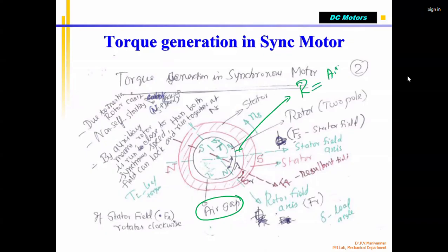Air is very poor compared to the stator and rotor, which are made of magnetic material. So that means for any given motor, whether AC motor or DC motor, the air gap should be small, but it should not be too small, because the rotor and stator should not touch. In an actual motor, air will be passing through the gap to cool the rotor and stator.